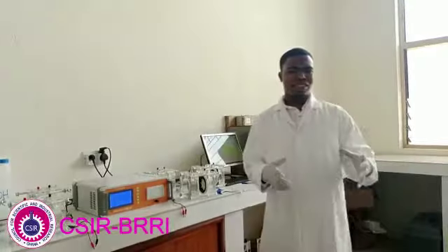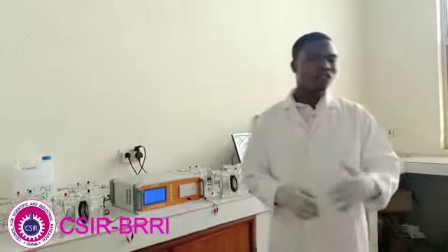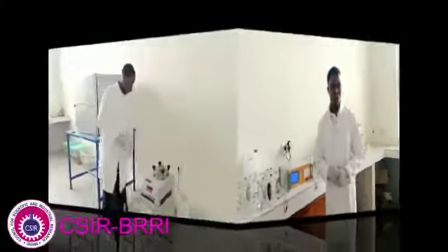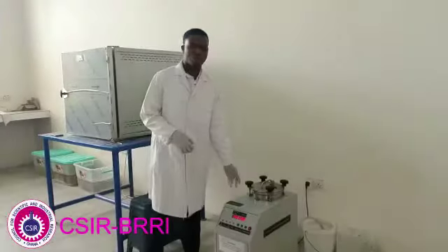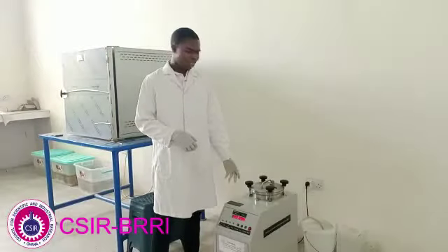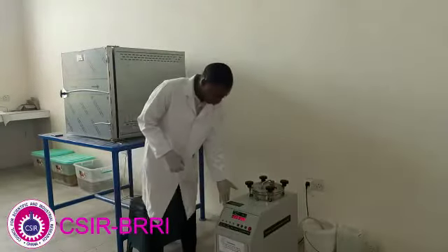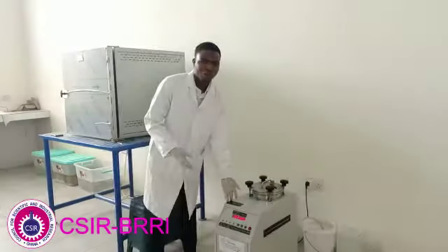First and foremost, before you conduct the test, you need to saturate your sample. In doing that, you saturate it for a dry period of 3 hours, a wet period of 1 hour, and then a static period of 18 hours. We have an intelligent vacuum saturation machine which we use in saturating the concrete samples, and as you can see, it's automatic. It works on its own.